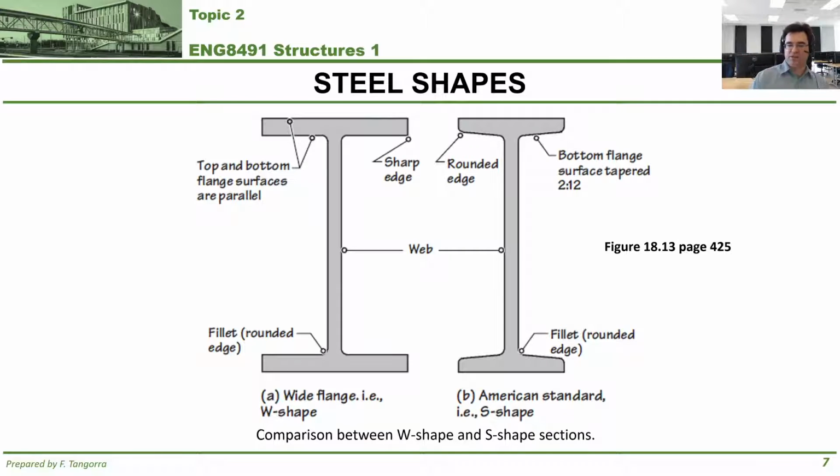The shape on the left, the W shape, or wide flange shape, you'll notice that it's more angular, right? Its angles are for the most part at 90 degrees. Also, the top part of it, the flange, the hat at the top and the bottom, is wide. So this shape usually is used when you have other beams or joists sitting on top of that shape.